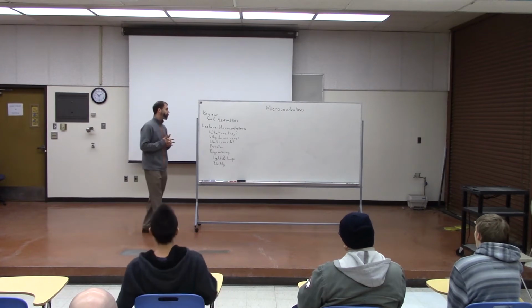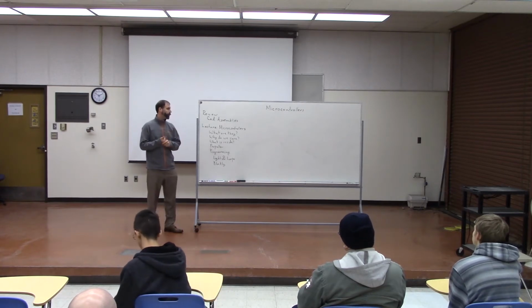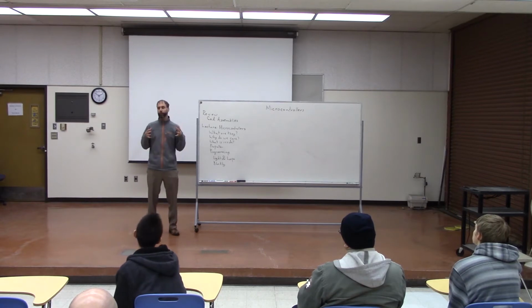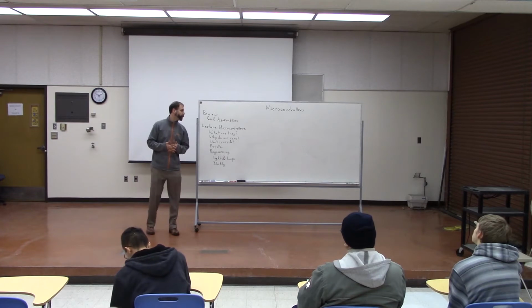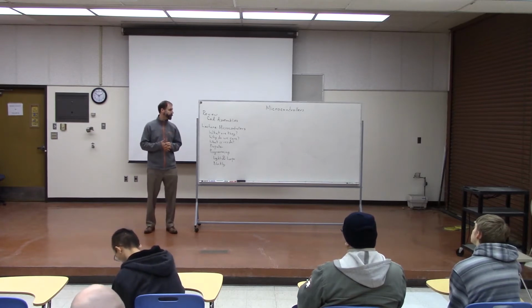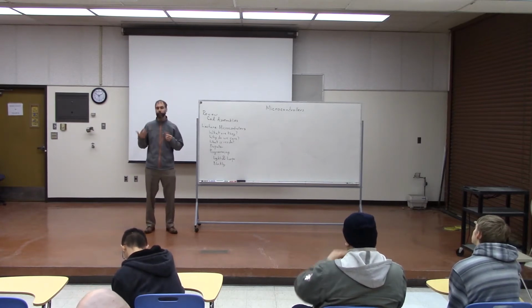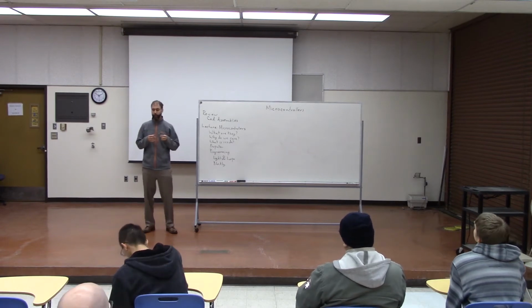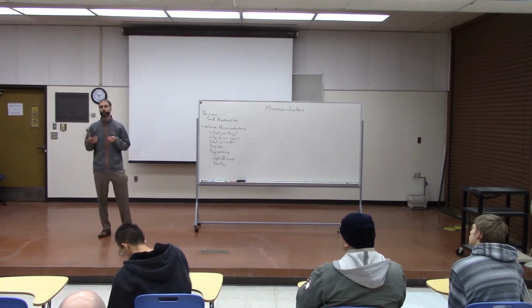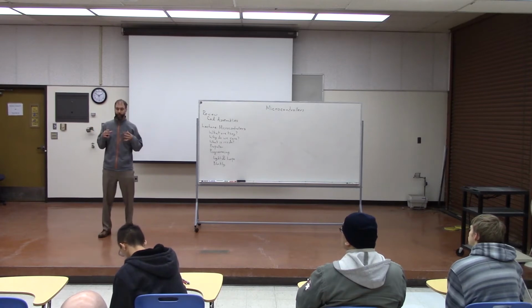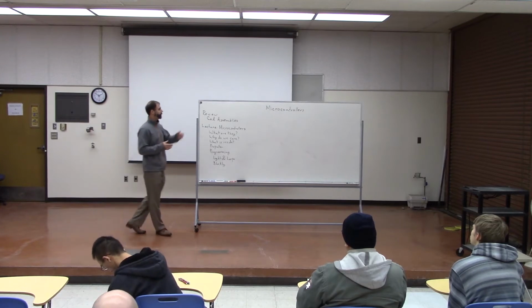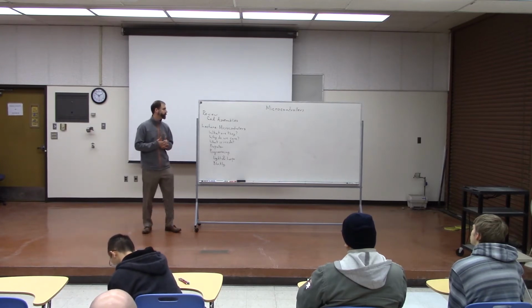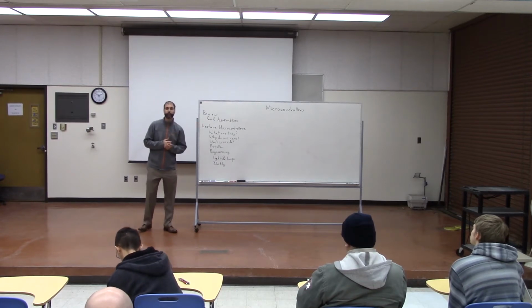Okay? So you start off by modeling parts, then you put them together using these constraints to create assemblies. And then once you have an assembly, you could use that to create a different kind of file, a presentation file, that allows you to do things like make animations and create exploded diagrams and things like that. So those were some of the fundamental abilities that we learned about with CAD.